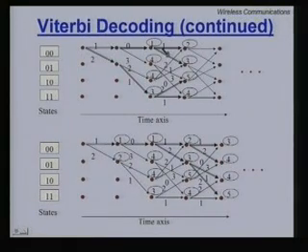We continue this process, and very soon we encounter the third stage, where 2 or more branches, in this example only 2 branches, are converging at this place. We go back to our philosophy that correct path should pass through correct nodes. So, we must take decisions at a node. At this node, I have to choose between this one or this one,